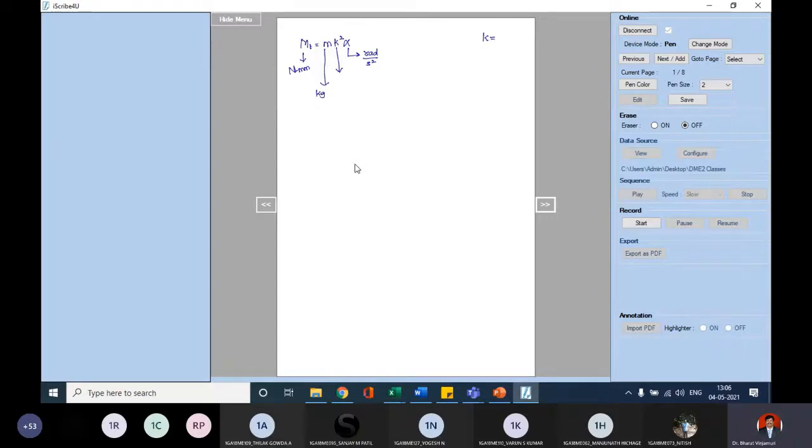So I repeat, Mt is the formula m k square alpha. And listen guys, what I am trying to do is talk about the knowledge point of view. If you don't have these basics and still feel you are going to become an engineer, that is not correct. I want this in Newton mm. M is by default in kg. Will I get Newton mm if I multiply all this? Alpha will be in radians per second square. What will be the unit of this?